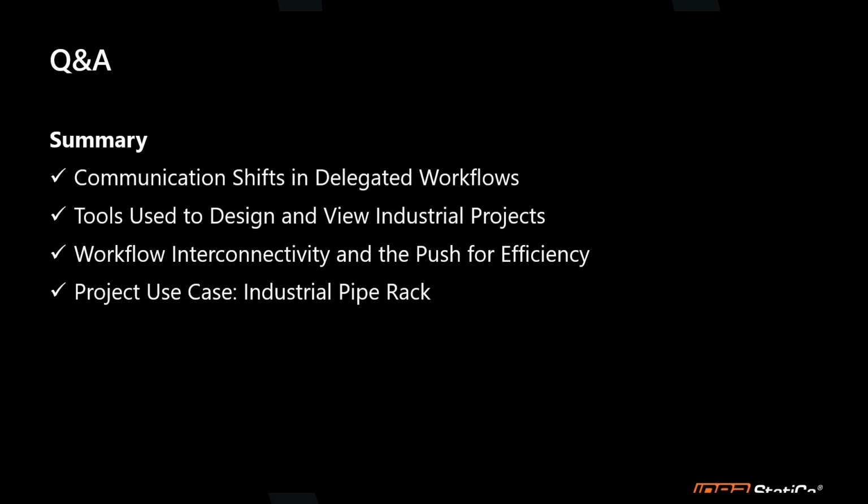force acting. That's why we have this option to shift the force along the member, either in a position, so you can tell from the node and at what position you want that shear force acting, or if you select bolts, it will detect if there is any bolt, and that will locate the shear force at that position. But it's really helpful to go to the software and click over the member, look at the transparent mode, and you will see the moment diagram. And where you have 0 moment, that's where the force is located.